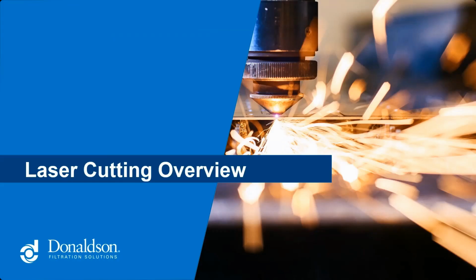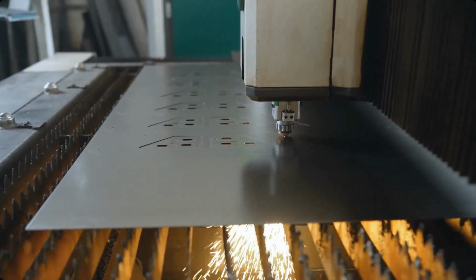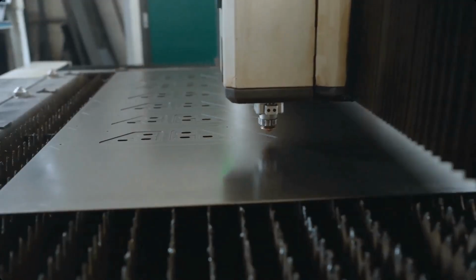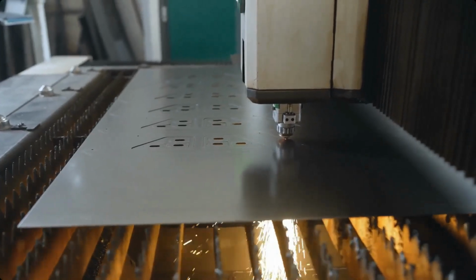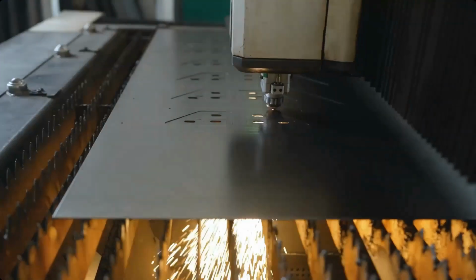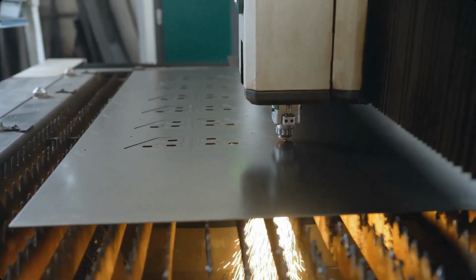So let's do a little overview here of laser cutting if anybody isn't familiar. A laser cutting machine is a device that uses a focused laser beam to cut through materials. It's a versatile tool used across various industries like industrial manufacturing for precise and efficient cutting, engraving, and etching of a wide variety of materials such as carbon steel. As you can see, the laser beam is generated and focused on the material to be cut. The heat from the laser creates a precise cut and is controlled by a CNC system.